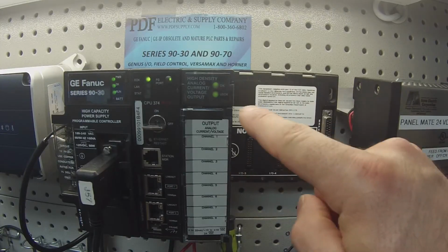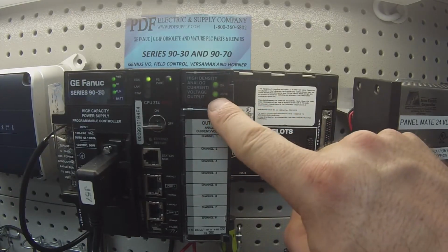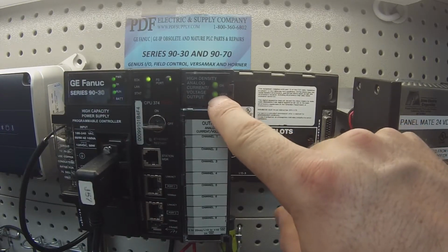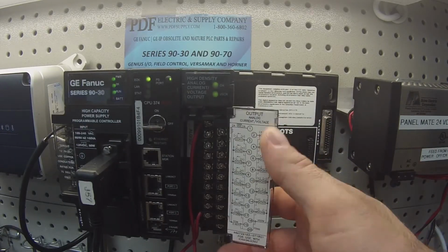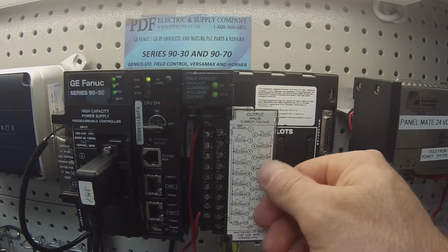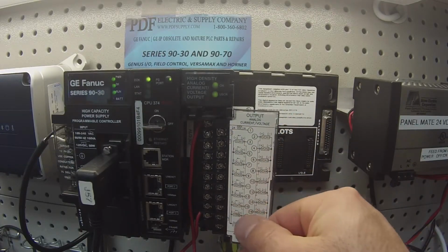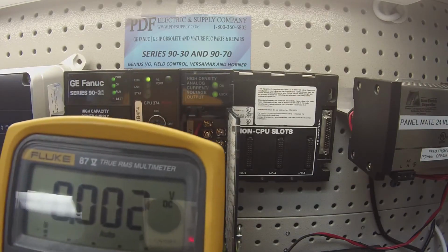Second thing is if there's something wrong with its ability to accept the 24 volt DC through the user supplied power supply. If this LED isn't on telling you that that's working properly, that's another problem. Third problem is the one that I mentioned before, where the output fails at full value. And the fourth one that we see is that everything seems to be working properly. You put a value in and you're not getting anything in return on your multimeter, it's just reading 0.